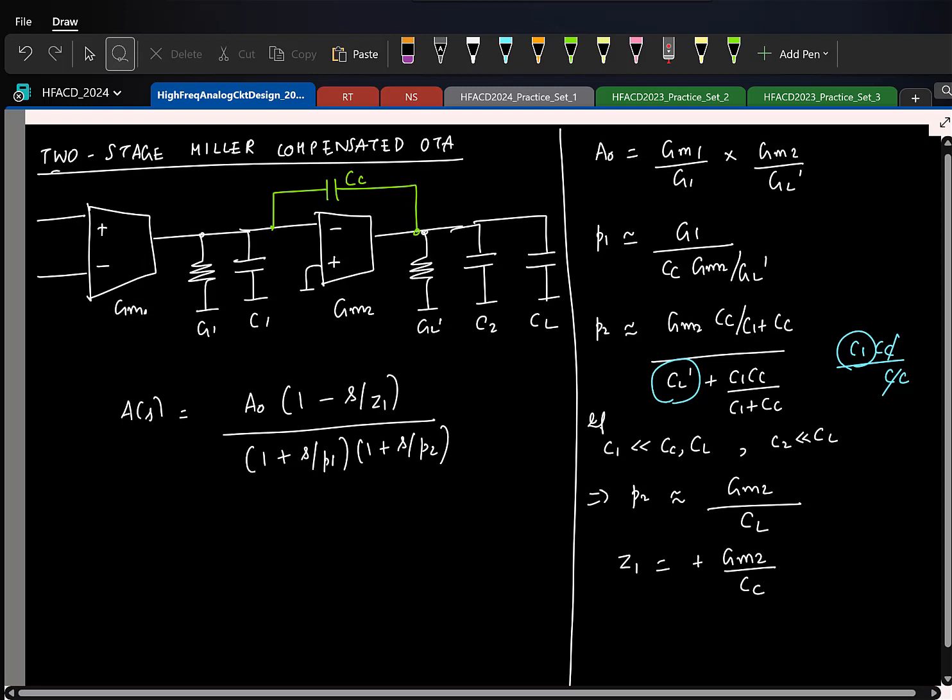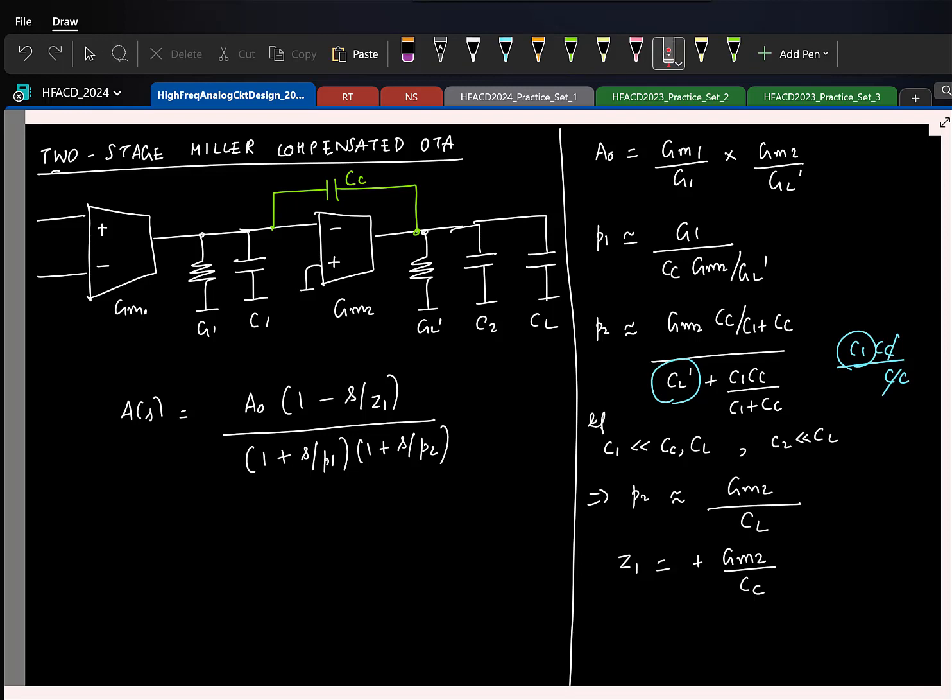Fine. Great. So now, what we expected here was the two poles getting split. That definitely happened. One drifted to a low frequency, one drifted to a high frequency. But what is something that was unexpected? Yeah, the 0 was something that we didn't expect. And we already know that this 0 being in the right half plane will degrade the phase margin. So let's try to get an expression for how the phase margin is going to look.